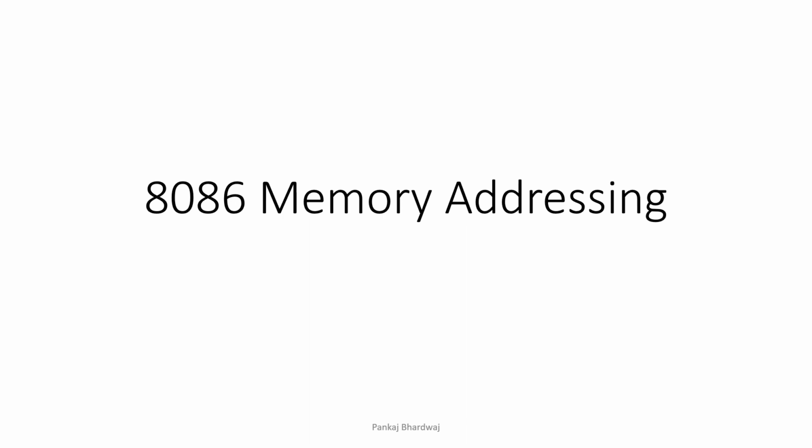Now let's discuss 8086 memory addressing. We know that 8086 has 20 address lines. That means 2 to the power 20 memory locations. That means 1 megabyte of locations can be addressed using the 8086 microprocessor.